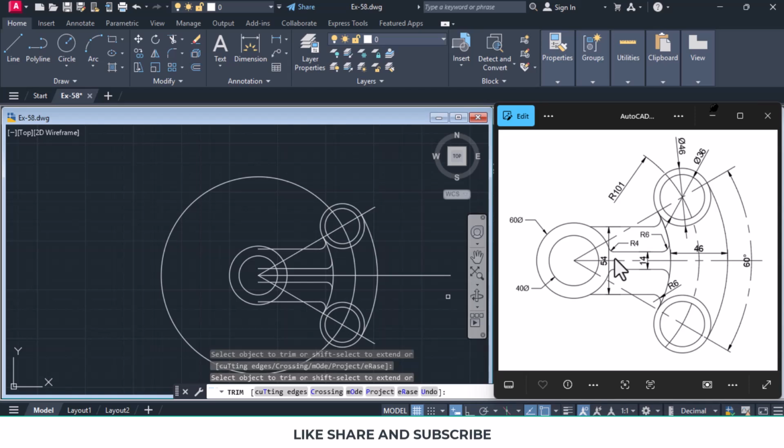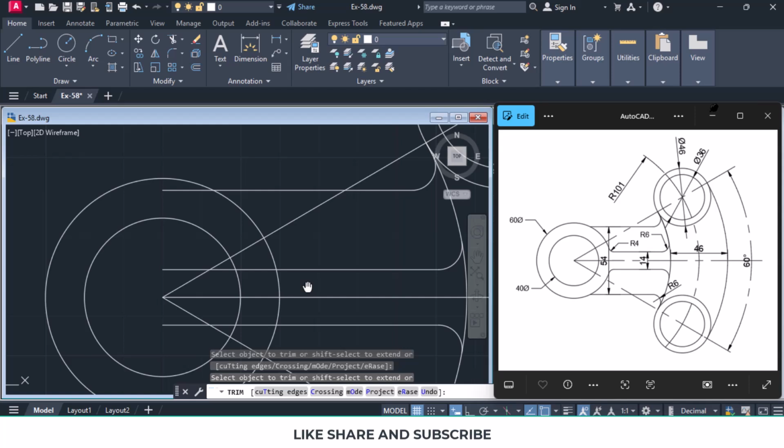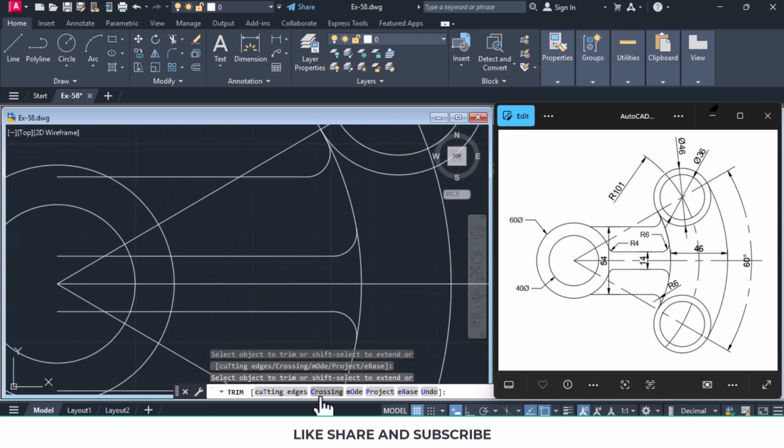Now these two fillets are at a radius of 4 units. So again we press F for fillet, R for radius, and radius is 4 units. Then we click on this circle and this circle.